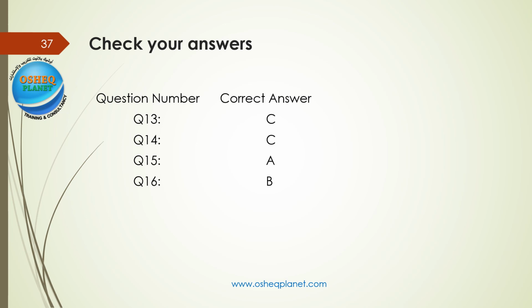Question 13. Employers must monitor all employees whose noise exposure is equivalent to or greater than a noise exposure received in 8 hours where the noise level is constantly 85 decibel. So, the answer is number C. Question 14. Baseline and annual audiograms are required in the hearing conservation program.